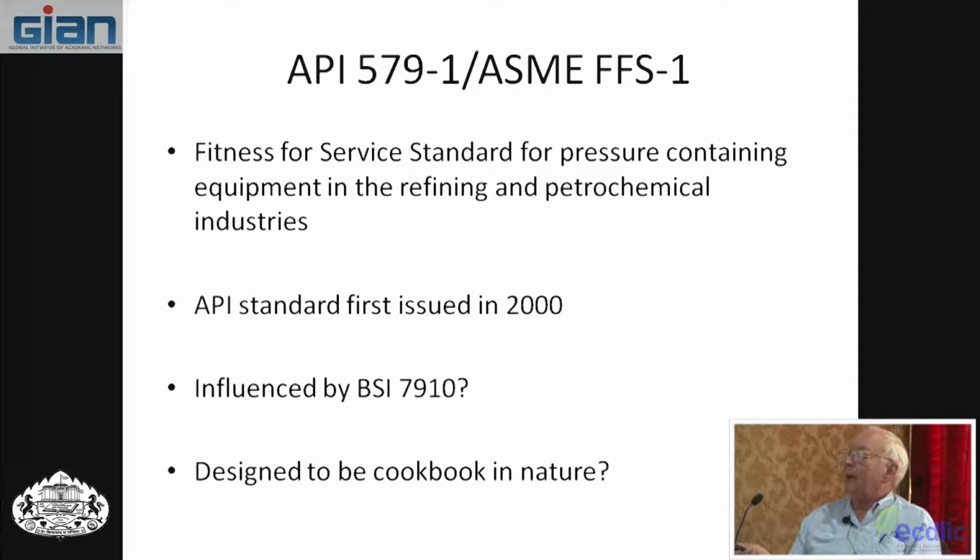Now, the petrochemical companies, oil companies like to use the CTOD, and they pretty much follow the British standards in developing their stuff. There is a thing, American Petroleum Institute, API 579-1, and now is also an ASME standard, and they have fitness for service standard for pressure containing equipment in refining and petrochemical industries.